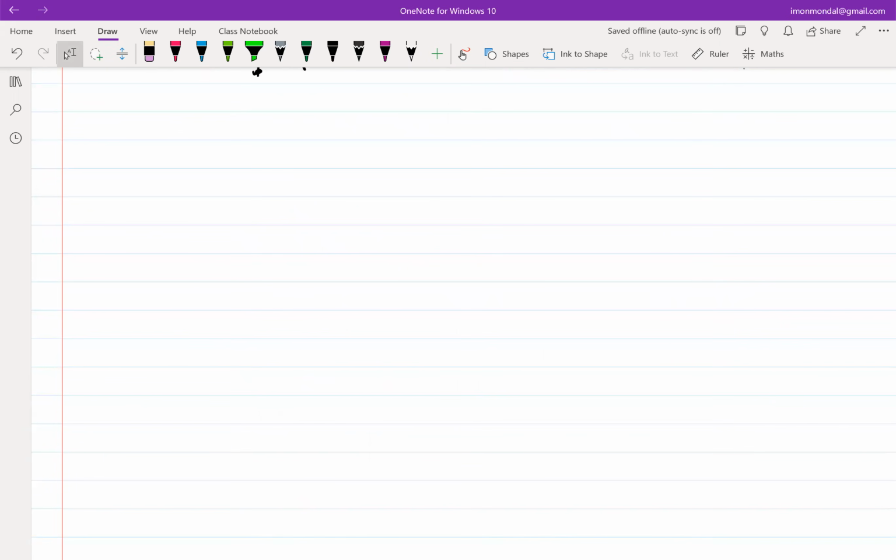Now, replacing a resistor with an active load is obviously not limited to a common source amplifier. Wherever you find a resistor which is giving rise to a gain, I mean, you are using the resistor to get a gain of GM times that resistor, which means that resistor can probably be replaced by an active load, right? So the obvious next step is to replace. We had this differential amplifier with a resistive load.